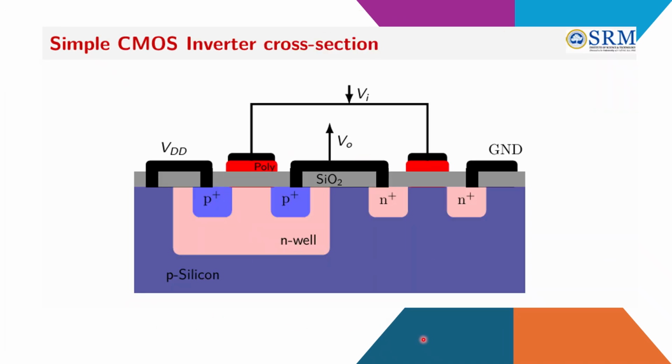So if I'm revising, this is the substrate, this is the well formation, then the drain and source formation, your gate formation, and then polysilicon and metallization. So these are the techniques.